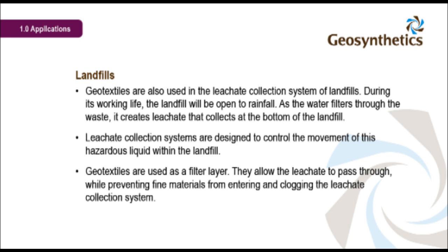Leachate collection systems are designed to control the movement of this hazardous liquid within the landfill. Geotextiles are used as a filter layer. They allow the leachate to pass through while preventing fine materials from entering and clogging the leachate collection system.